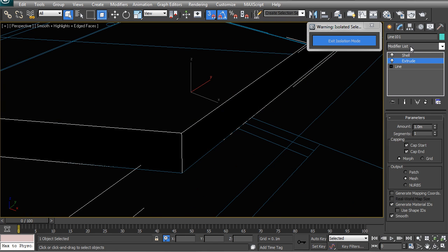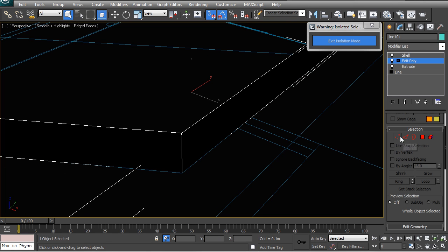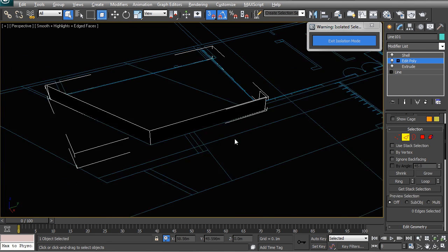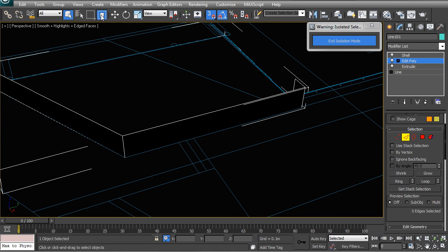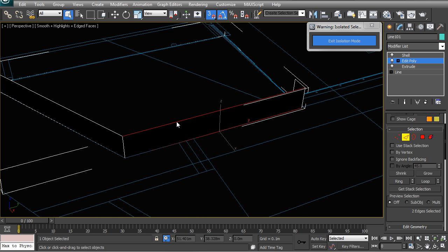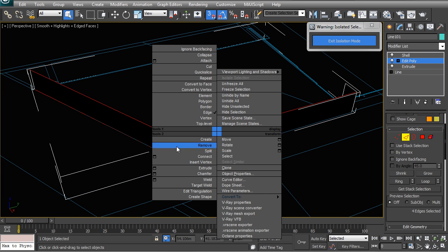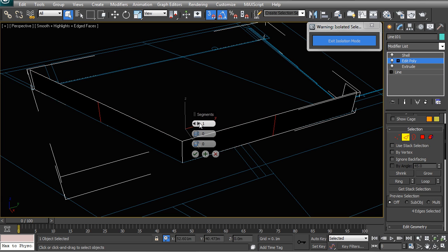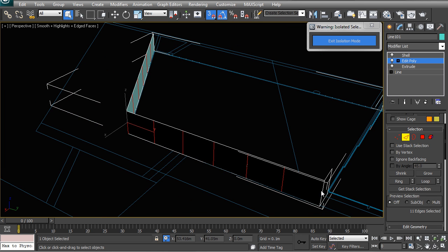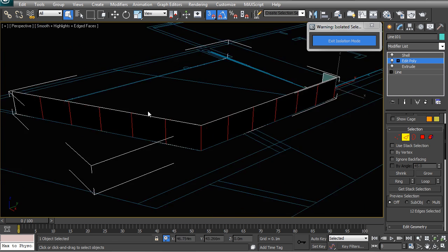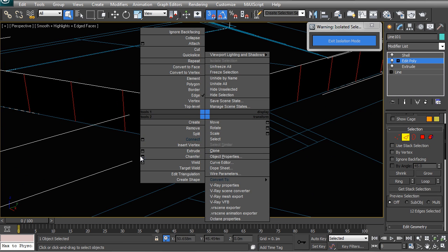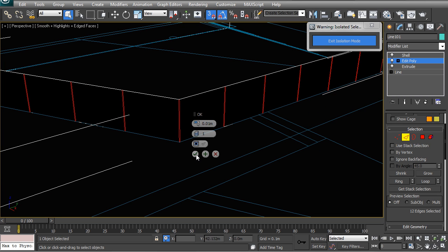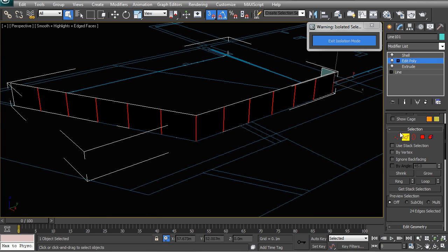And the other thing that we want to do is, for more realism, let's add a couple of panels to our glass balustrade. So what we can do here is, with the crossing selection, we can choose these edges, we can right click and then connect them a few times until we see that the panels look correct. So not too many, not too few, about 5 should do it. And then selecting including the corners, let's now go and right click and chamfer that. I think about 1 centimeter should be fine, so a gap of 10 millimeters.